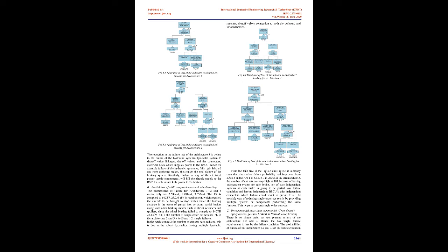Architecture 3 of the brake system considers the right and the left side to be fully independent, with independent hydraulic system A for the right side and hydraulic system B for the left side brakes, and independent BSCUs. The BSCU further has independent cores for the inboard and the outboard brake of the right side and vice versa. Hence there are totally 4 cores, in which each core controls each independent brake. The parking brake architecture is similar in all the brake system architectures.